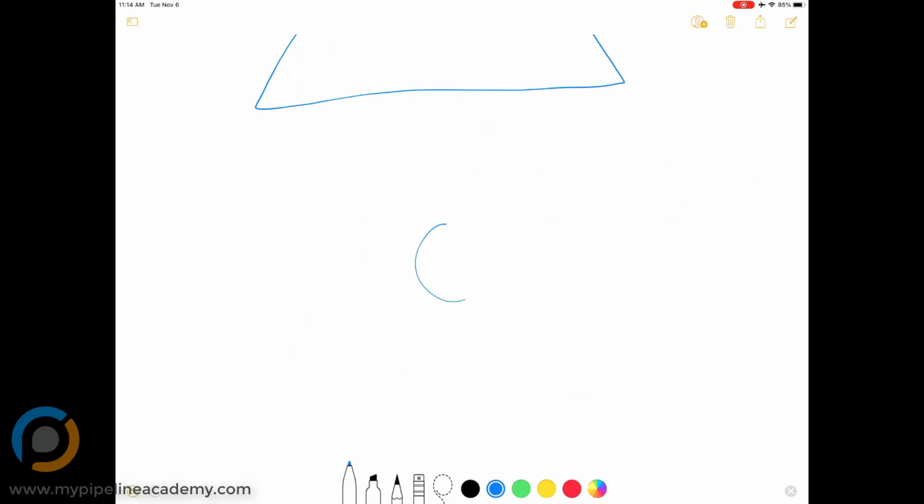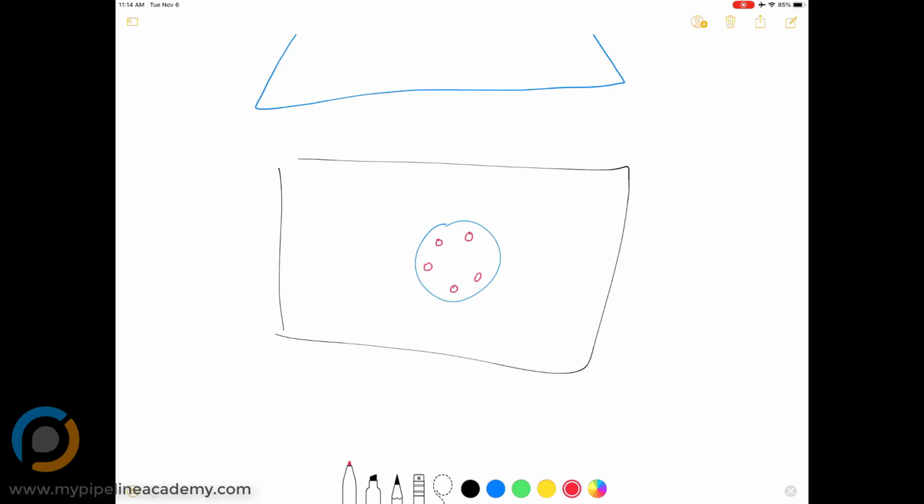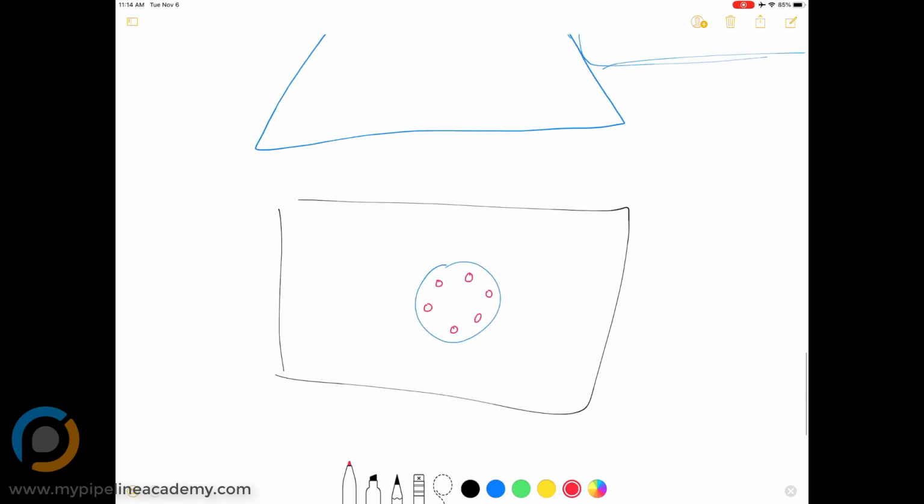So if we draw this again, we've got our flange, and we've got our light that kind of surrounds it. The only part of that flange that's actually holding the light is these screws, the diameters of those screws. So the second equation that we could do is... So then we figure out, we gotta get on the McMaster website, find out the radius of the screw, or the diameter of the screw. Yep. And then we find out how many screws we need. Right. Because all the stress is gonna be on the screws. Mm-hmm.